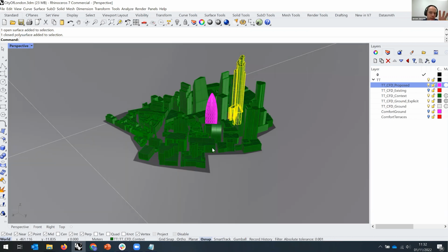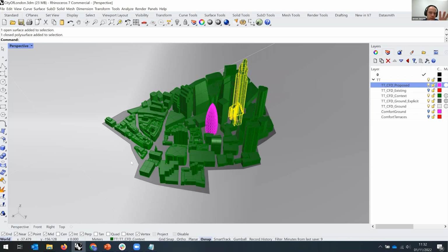But that's the range. And again, the number of buildings you need to include is a similar thing. I typically do 1 to 1.5 times that height, unless there are some tall buildings that still could influence the wind, then you do include them. That makes sense.